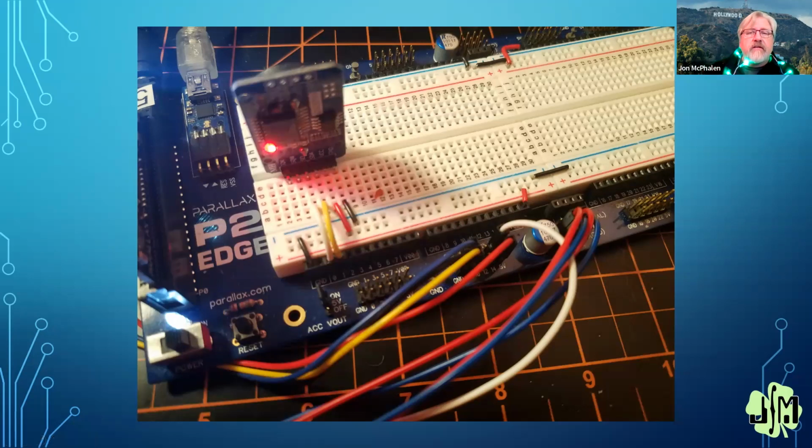You have to set it to 5 volts, but at least for the basic and the enhanced units, which is what we're using, the serial levels are 3.3 volts. There is another thing called the intelligent display that's got a red or orange PCB that uses 5-volt IO, so you need to put a resistor in for that.